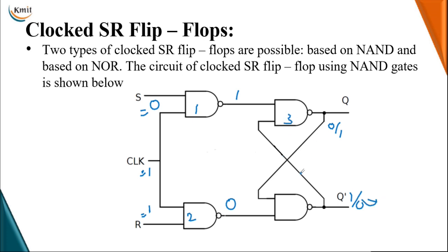Immediately the fourth NAND gate output will be transferred to a logical 1. Since one input of the fourth NAND gate is 0 and that is transferred as the second input of the third NAND gate, the present state is 0 or 1 and the next state is equal to a logical 0. Since our input is 1, we obtained a state called the reset state here.